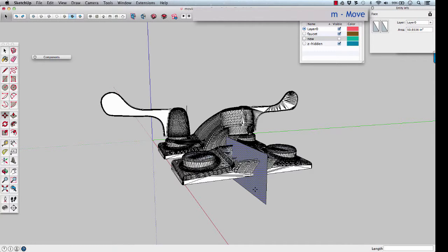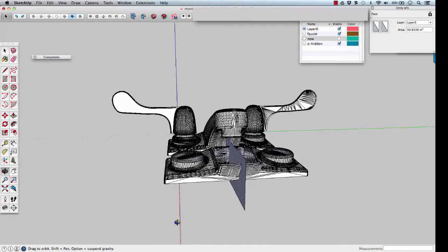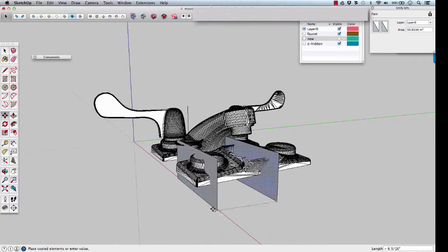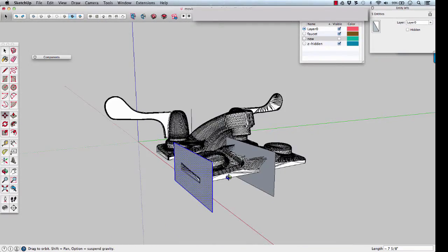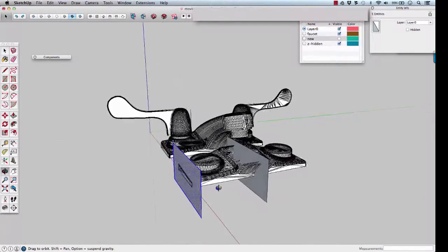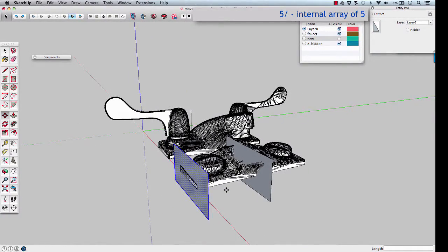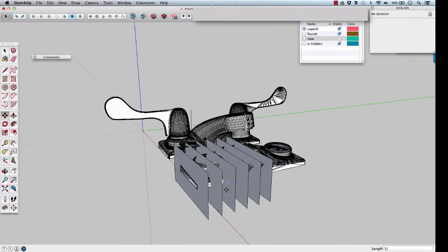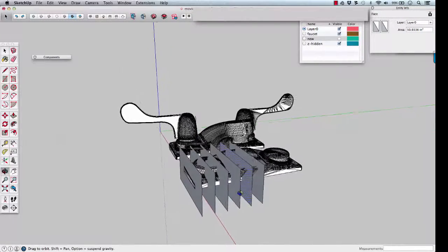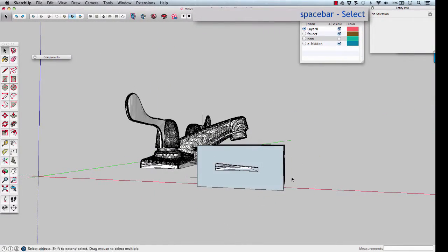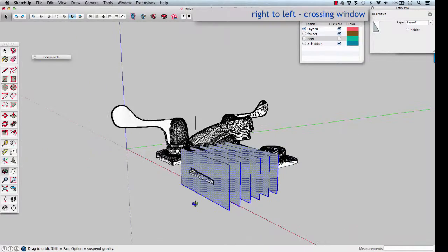Select that plane, and with the Move Copy tool, I'm going to copy to the other end in the green. The back looks like it's the best point to pick. And then I'm going to choose to do 5 segments within that, 5 divisions. That would create profiles for me to connect to form the base. I'll select with the space bar, or 6 total I guess.